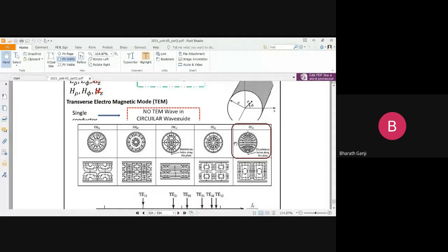But if you make it 2, then you get symmetry in two half planes. Like, maybe I cannot draw it here, but if you see, I have taken TM02. You can see that whatever pattern repeats in this half plane, actually not even half, this quarter plane, the same pattern repeats here with opposite sign, another with different phase. That means cos 2φ comes into the pattern.